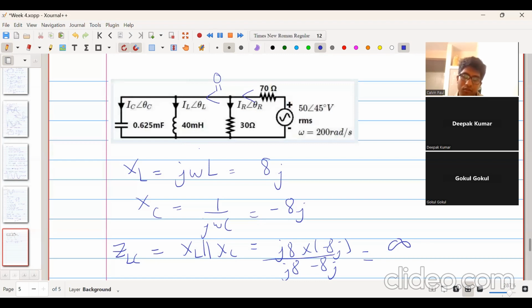In resonant frequency, the voltage will decrease from its initial value. No, there are different resonances: series resonance and parallel resonance. So this is the parallel resonance concept. In series resonance, the current is maximum, and there will be voltage magnification across L and C. In parallel resonance, there's the concept of current magnification flowing through L and C. We'll just solve this and not get into that.